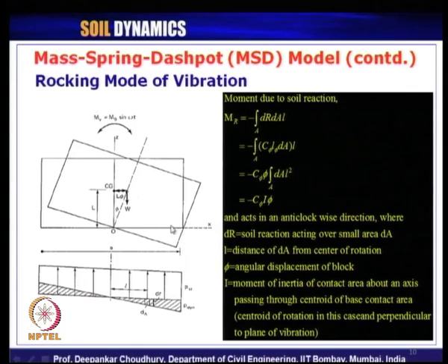What is the pressure distribution going to be developed below the footing? There is a static uniform pressure and then this variable dynamic pressure at the base of the footing. Because of that, what moments are getting generated? Because of this dynamic, unbalanced pressure, some moment will be generated. So, moment due to soil reaction is nothing but that component. Then from the displaced position of the CG, some moment will get generated, and this is the externally applied moment. So, the sum of these three moments will